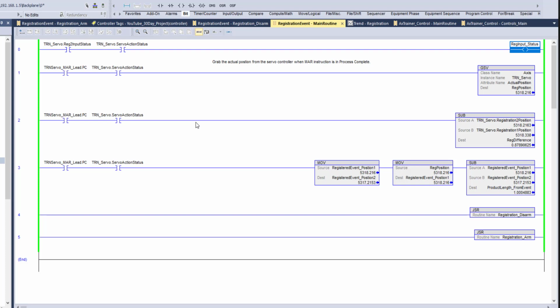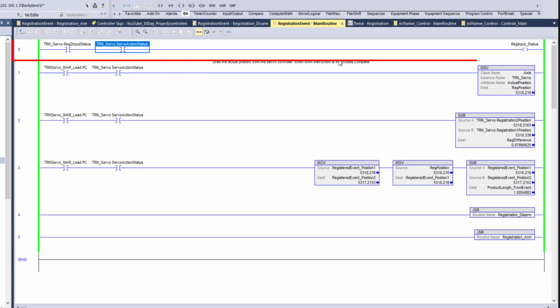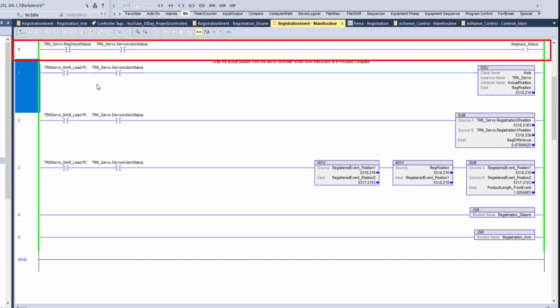Are you using the normally open side of the photo eye, or the normally closed side of the photo eye? Are you transitioning when it makes the reflector or when it breaks the reflector? That is the actual thing you need to realize. Okay, I'm going to show you this. Okay, so I'm actually doing this when the photo eye is made. I'm coming in giving this registration. Now I'm giving the registration event.